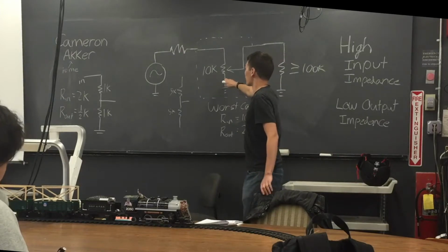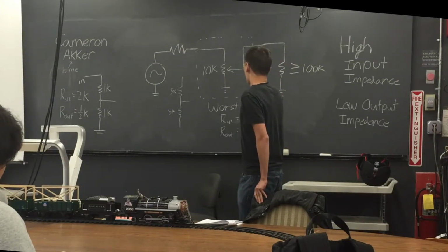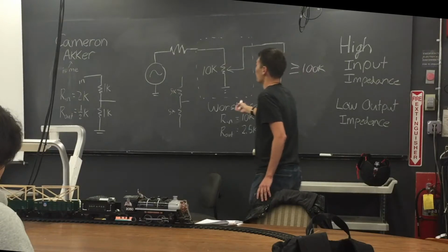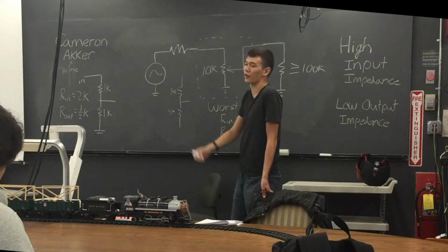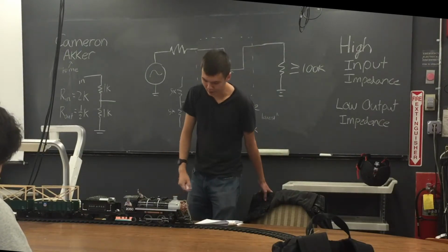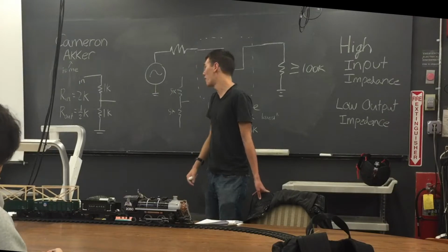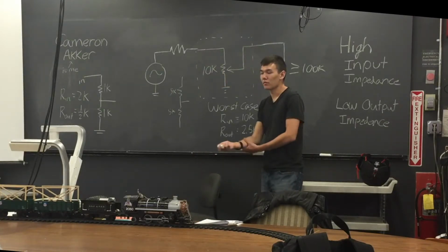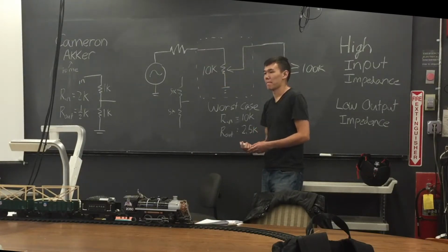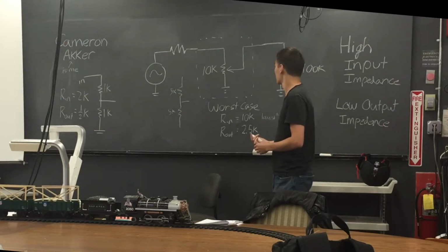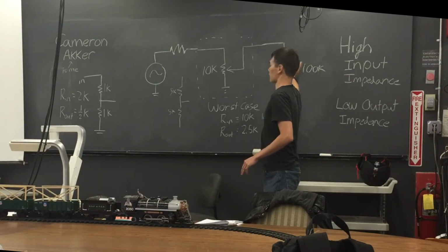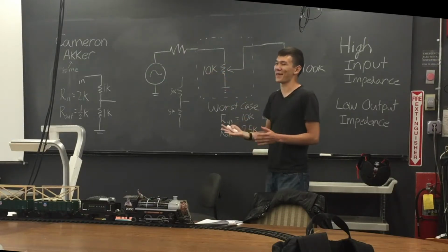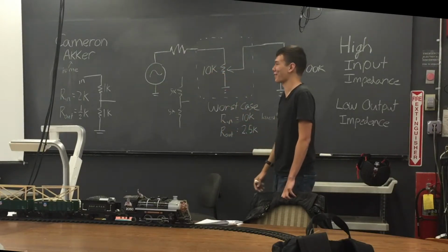What 10K does do, though, is since your input impedance is 10K ohms, that means your output impedance per unit stage has to be 1K ohms. So it limits a little bit there, but not significantly. Yeah. Okay, I think the problem is I was thinking of it as your output, say in the middle, is going to feed your input on the next component. Yeah, the next one. You always want to compare this output to this one's input. It's easy to say, but making that actual mental connection is a little bit tougher.